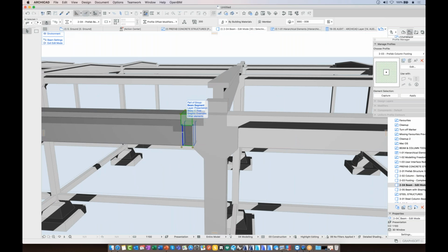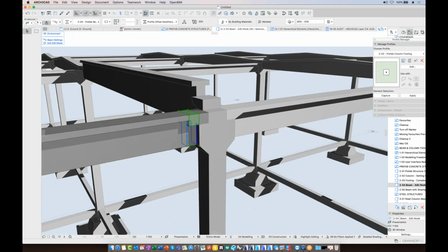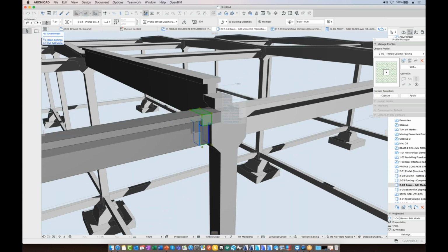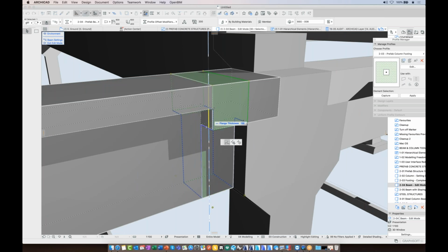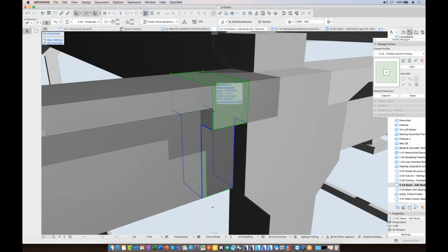And now we need to get the tapered angle here to make this look nice. So I'll select the geometry. And we need to come up here to the info bar where it says cross-section size and change this to tapered. And now, while in edit mode, I can achieve a taper graphically.